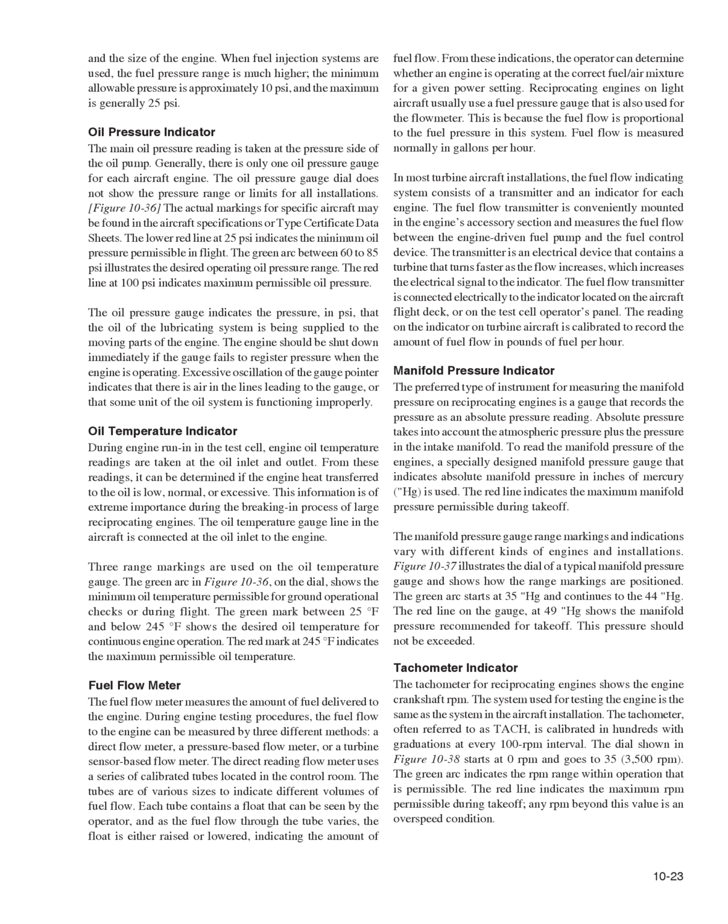Oil temperature indicator. During engine run-in in the test cell, engine oil temperature readings are taken at the oil inlet and outlet. From these readings, it can be determined if the engine heat transferred to the oil is low, normal, or excessive. This information is of extreme importance during the breaking-in process of large reciprocating engines.